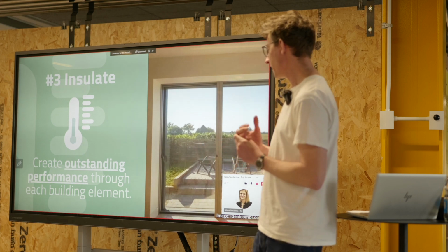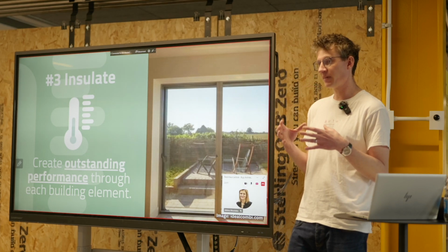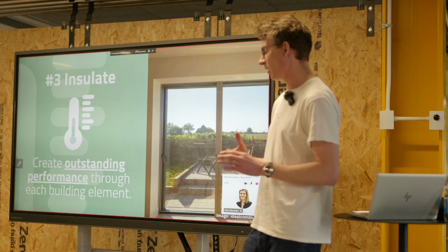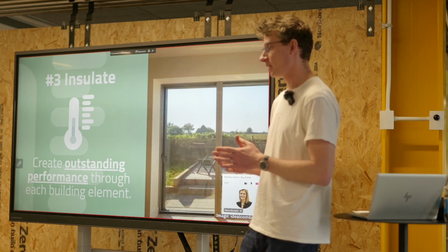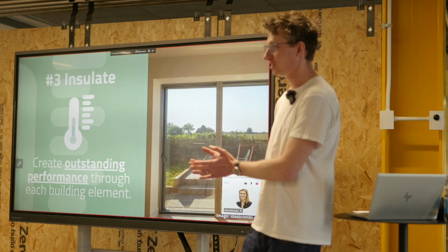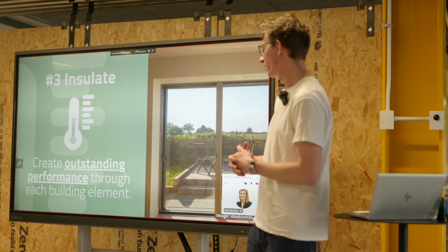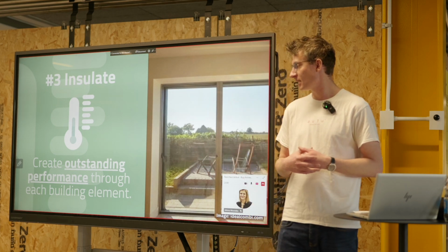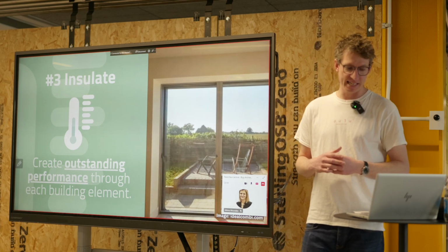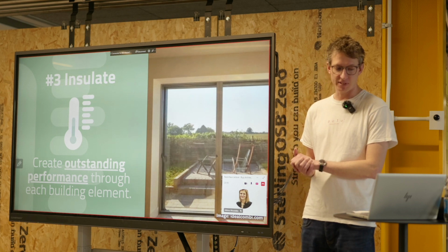Passive house design, one of the fundamental aspects of it is to have a highly insulated building fabric. You've got huge amounts of insulation in the walls, in the roof, and in the floor, and that obviously takes up more space. So if you end up designing a project up to a certain level and you put in more conventional wall thicknesses, trying to add that thickness later on in the process can be a challenge, with constraints or budgets or whatever. So making sure that you've got realistic wall thicknesses in from the start is really important.